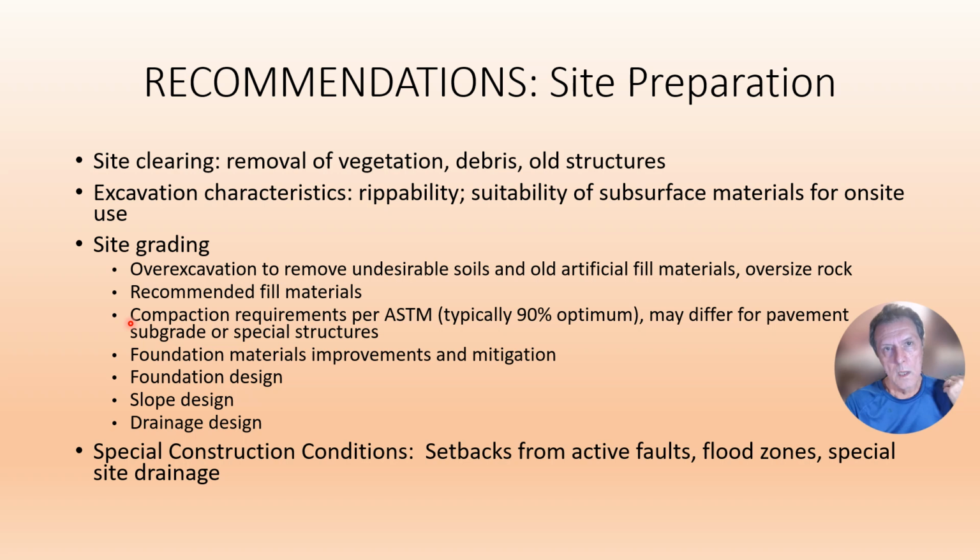Any soil or processed rock which is used to build fill pads for structures is subject to compaction requirements per the American Society for Testing and Materials, typically a 90% compaction at optimum moisture. Those requirements may differ for pavement, subgrade, or special structures. You want to discuss in your recommendations any improvement of the foundation materials. Do you have to get deep compaction to improve the materials for some types of foundations?